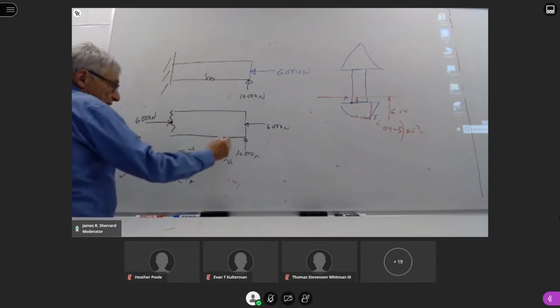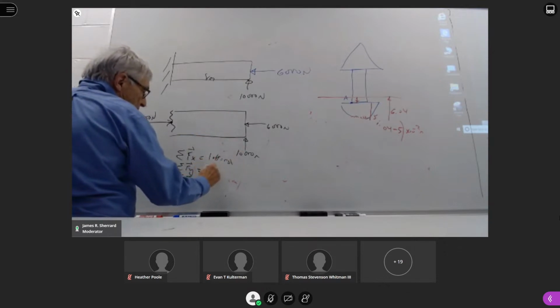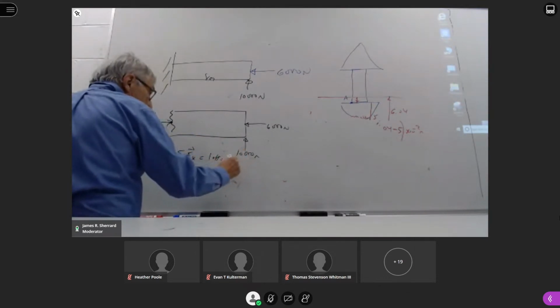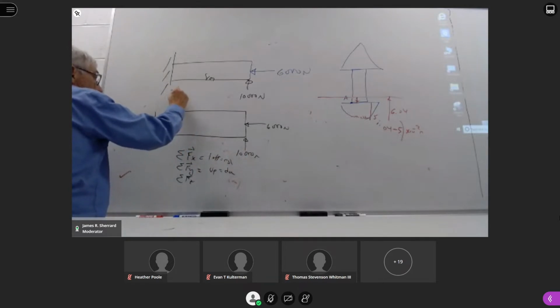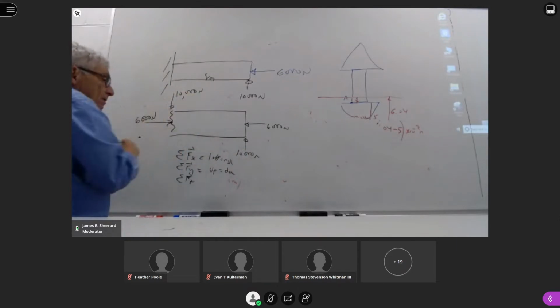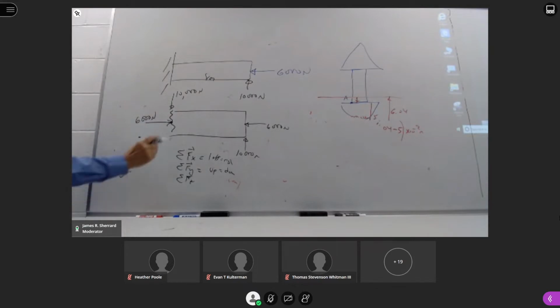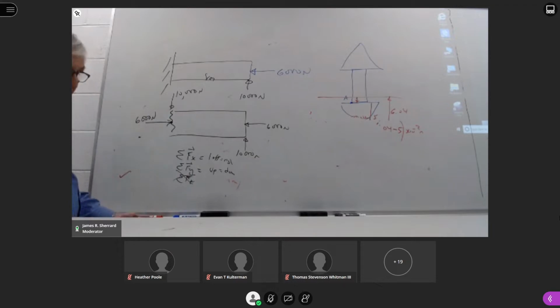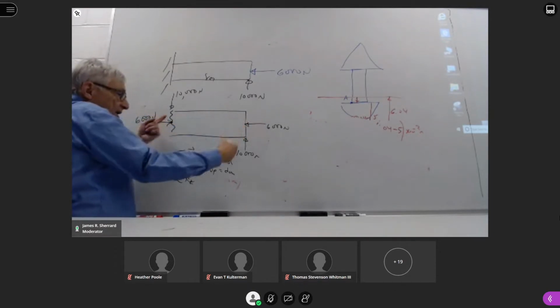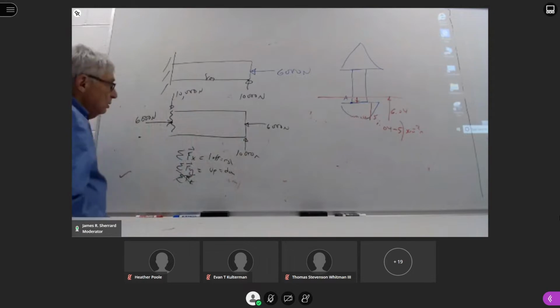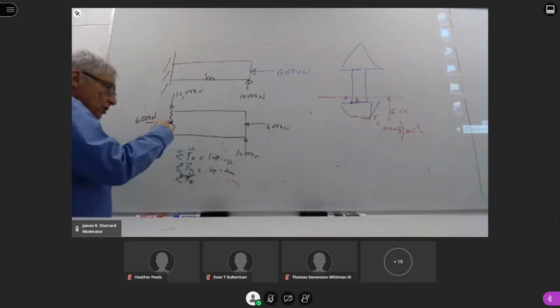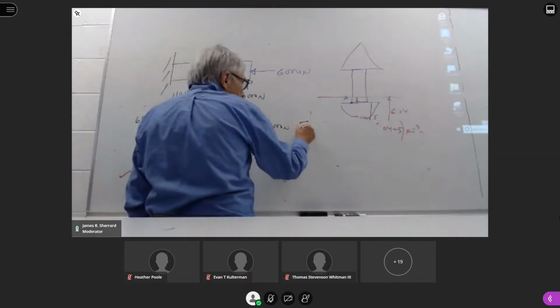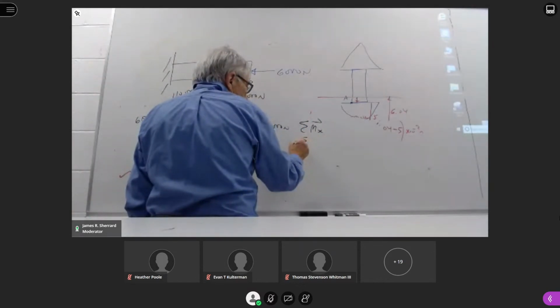If we look at forces in the y, yes, we do. The ups have to equal the downs. And just like before, this has to be that way. There's nothing for forces coming in and out of the board, so this doesn't count. It's 0. That isn't complete, because if you look at this, this sort of cancels the other out, but this still makes it want to go counterclockwise. So we're going to have to look at sum of moments around each axis.